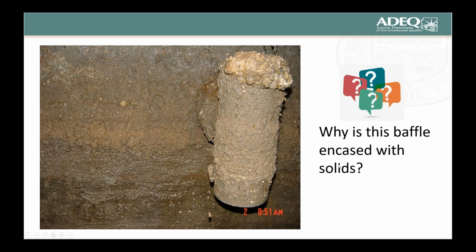Why is this baffle encased with solids? Same thing. I'm not sure whether this is inlet or outlet, but everything got too high, especially if there's any partial pluggage or major pluggage on the outlet of the septic tank.